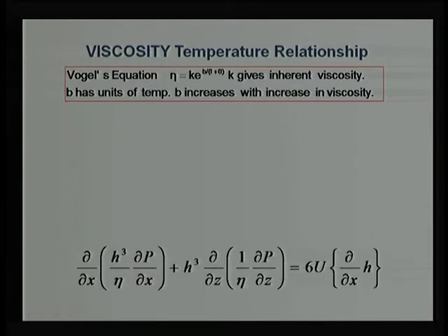This is the reason why we require an energy equation to be incorporated, where the pressure and temperature relation may come one way or another way. There is some sort of coupling between pressure and temperature that can be accounted, and then based on the simultaneous solution of pressure and temperature, we can find out what will be the variation in viscosity with respect to temperature.